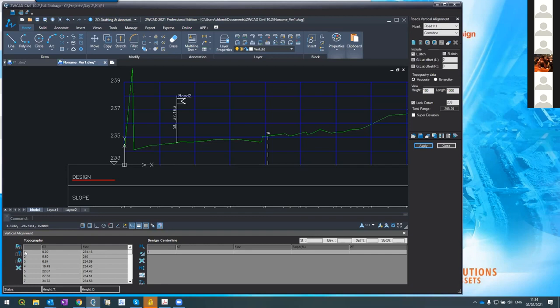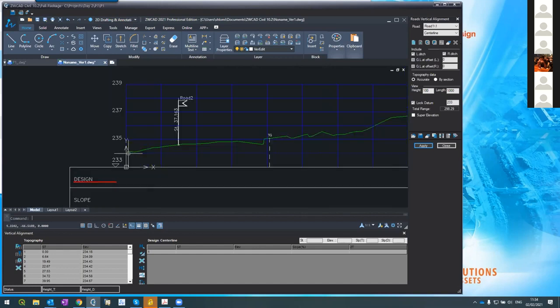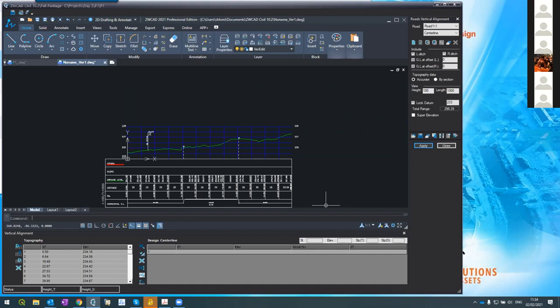I can change it manually, or I can just go to the serial number here. See, there's 1, 2, 3, 4 for each intersection point. I go to number 2, serial number, and press delete on my keyboard. Then the system completely removes this change. If I press apply, you see? The system just ignores this break and continues to the next break. I hope you got it. If not, I can try to explain again. You want me to repeat, or you got it, or it's not that important for you? No, I hope it's not too complicated. Anyhow, let me continue.